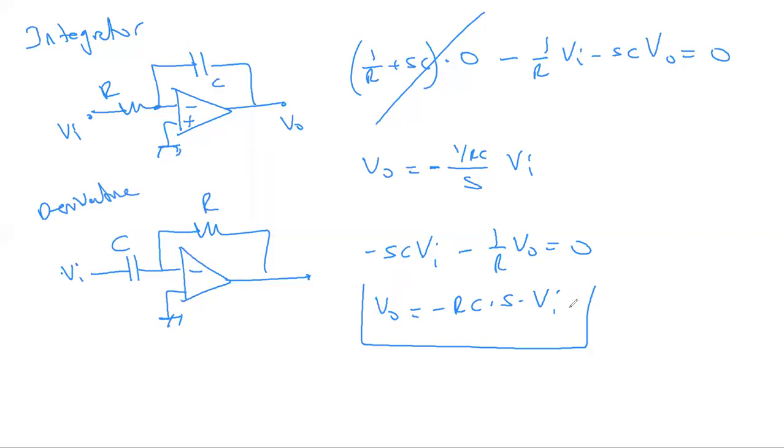If you take the derivative of a signal that has high frequency noise in it, then the derivative of the high frequency term in a short amount of time is going to show relatively high changes. Therefore, you are going to amplify the noise.